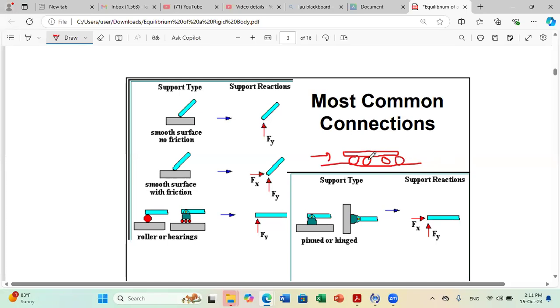So the roller can prevent motion in this direction, parallel to contact line. No. But if you put on it a force that is vertical downward, will the cart move down? No. Why? Because at rollers you have a reaction force opposing downward motion.